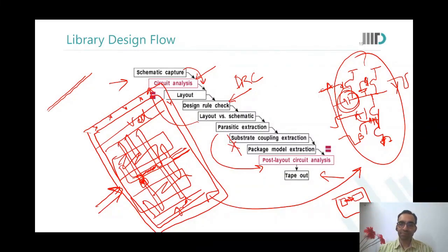So, sir, when we get to know about the parasitic extraction, are we connecting these capacitors manually ourselves in layout again? Or would there be any option for us to check this parasitic extraction after the LVS check? See, in the layout, you made those wires already. So those parasitics are already there. You don't need to do anything else. They're already there. They're parasitics. They're not to be designed. They just appear. They're parasites. You made a wire, and with it a parasite came.